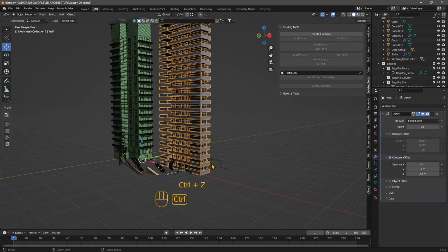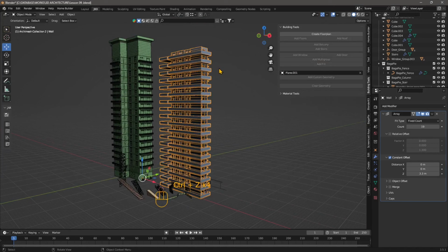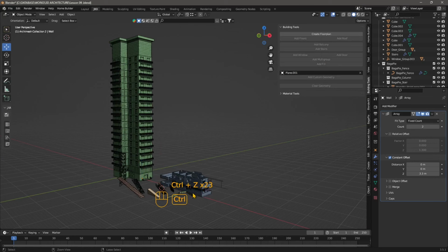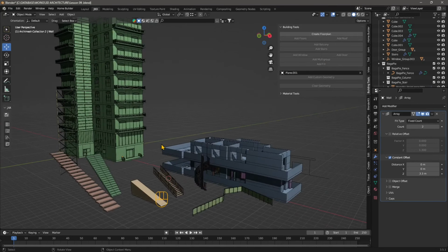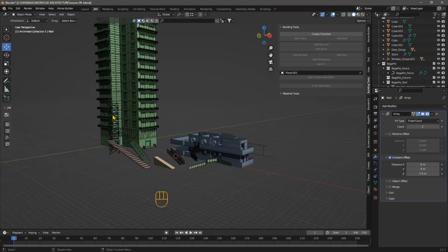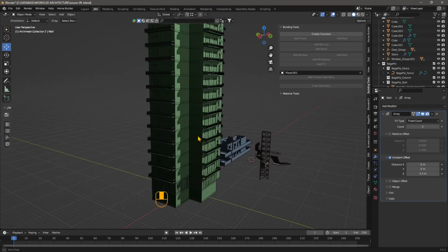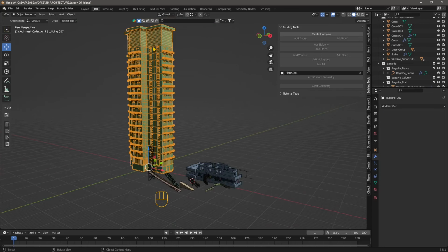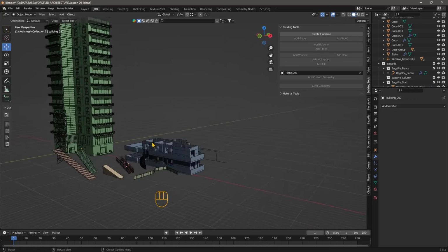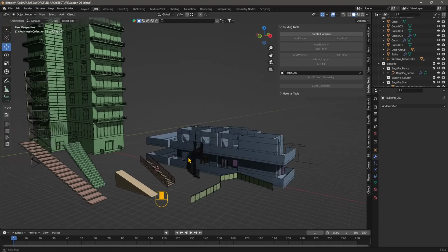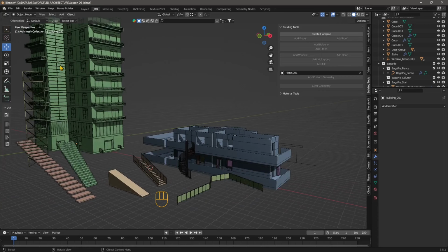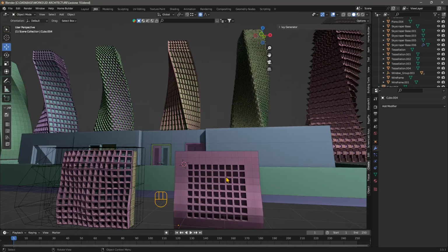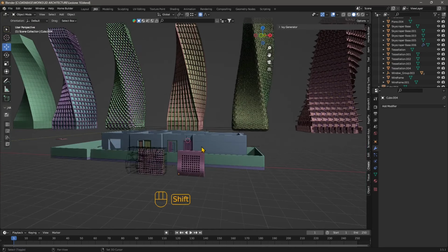Now, also in this video, we're going to see examples of how we can use standard tools in Blender, like polygonal modeling and mesh edit tools in combination with other generative design add-ons and tools and techniques to create something more complex. So in this case, with building tools, we can create really standardized buildings. But if you want to do something more customized, you can use the other tools that we're going to see in this video. So I'm going to show you quickly in another lesson here some objects that I've created so that we can create it together.